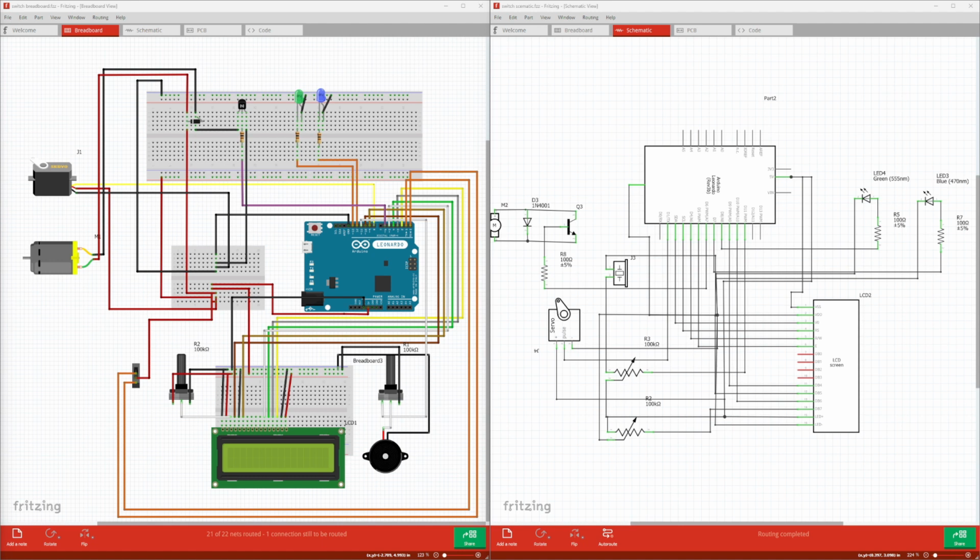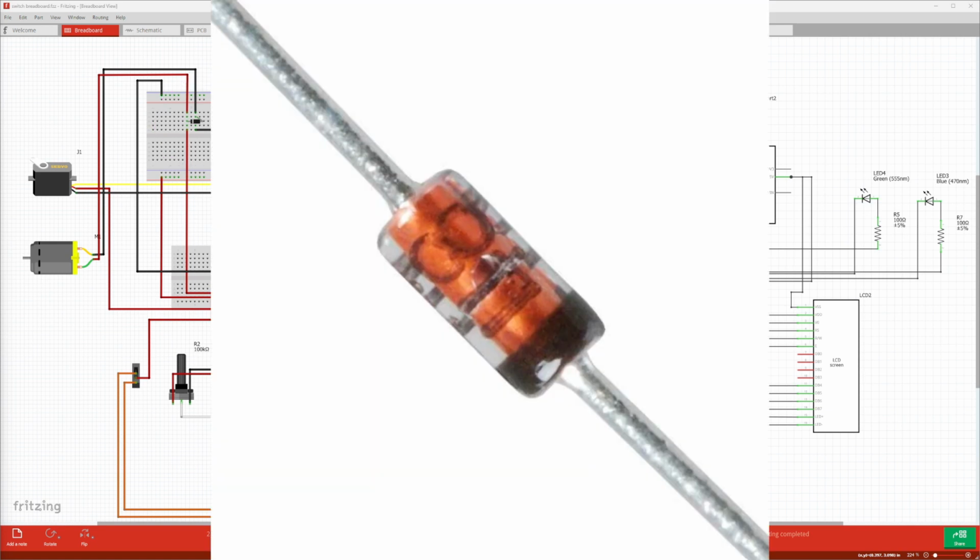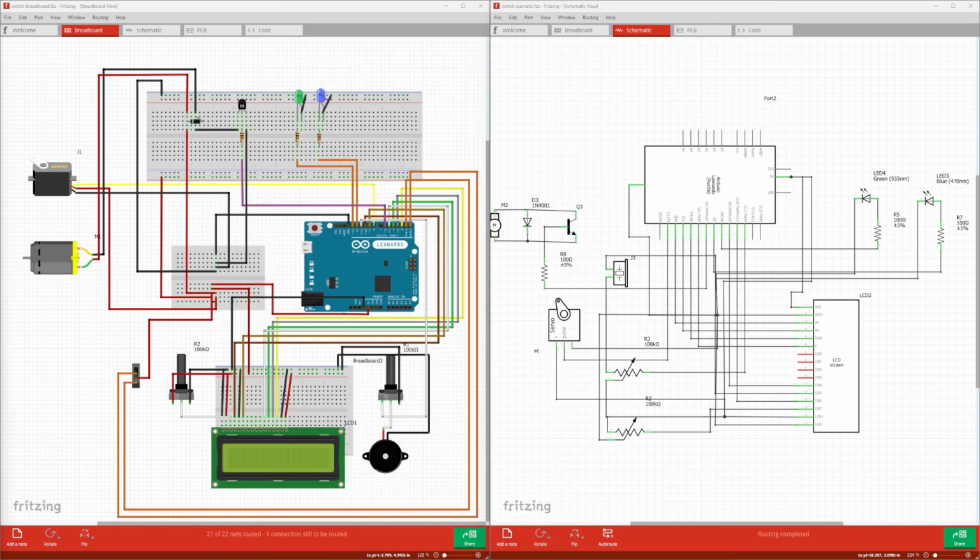When the motor turns off, the electromagnetic field collapses and causes a current spike which can damage our parts. To prevent this spike from damaging the components, I use a flyback diode. A diode is a one-way valve. A flyback diode is any diode connected across an inductor used to eliminate flyback, flyback being current going in the wrong direction. The speed of the motor is either off, slow, or fast, as are the 3 states from the switch.